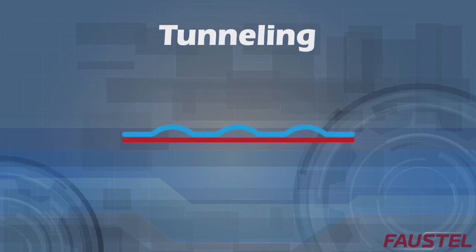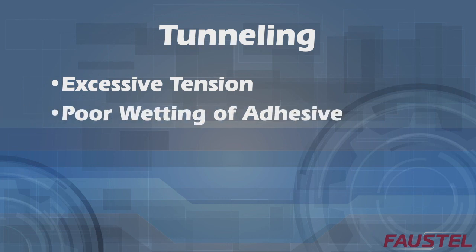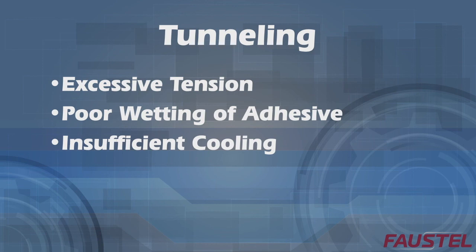Our last laminating defect, tunneling, is a defect that is synonymous with poor adhesion. It is a manifestation of insufficient bond strength to overcome the elastic forces of incorrect web tensioning. Examination of the web will show which one is under the highest tension, since the tunnels will be in the low tension substrate. From there, adjustments can be made to equalize the tension of both webs. Additional causes of tunneling include poor wetting of adhesive, which causes the film to separate in those areas with low adhesive concentration, and insufficient cooling of the webs after lamination.